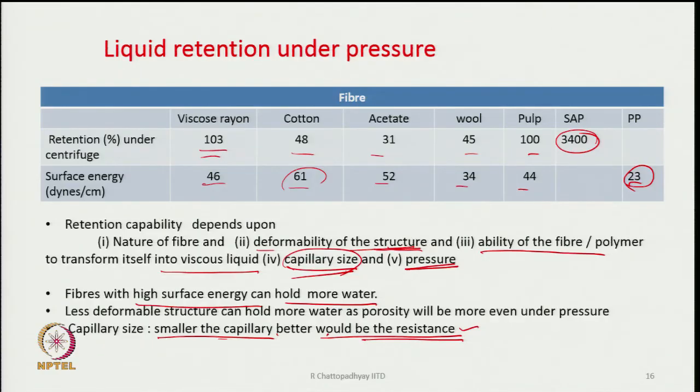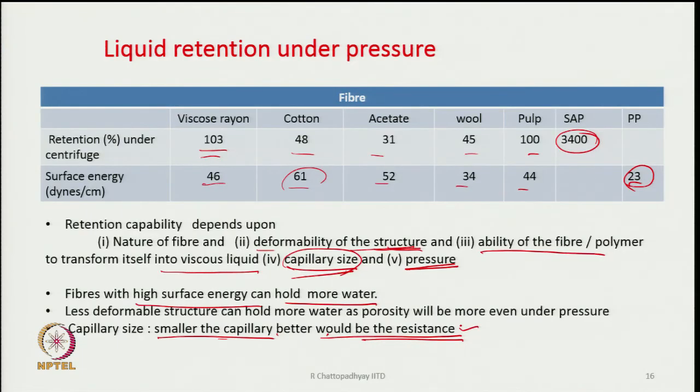If I use them thinking that I will try to improve the retention power of the capillaries, with finer capillaries, which can only be made from fine fibers, then the structure deformability is going to increase. Therefore, under a given pressure it will deform more, and the pore space available in a deformed state will be much less, and therefore, most of the liquid will flow out. These problems are there, and we have to strike a balance.